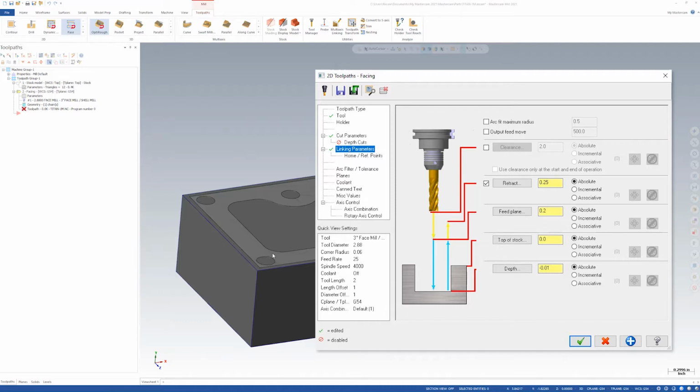Positive is above. So if we have it set to absolute, it'll always be that way. And if we always set it to absolute, it'll reduce that chance for error because of consistency and clarity, knowing that anything negative is engaged, anything positive is in space and safe.